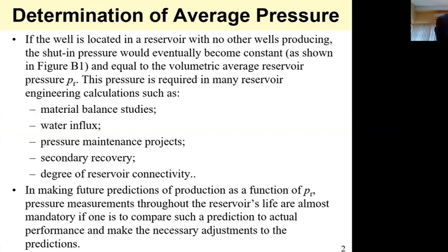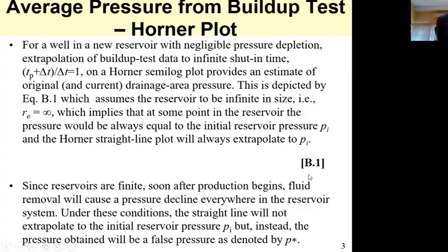And since making future predictions of production is a function of the reservoir pressure, determination of average reservoir pressure is important so that predicted pressures can be compared to actual pressures and necessary adjustments can be made.